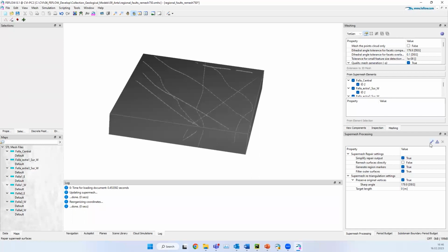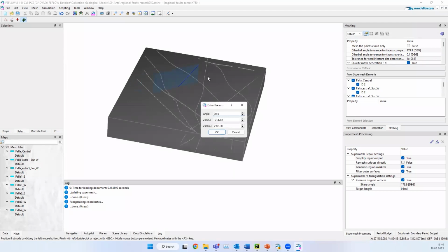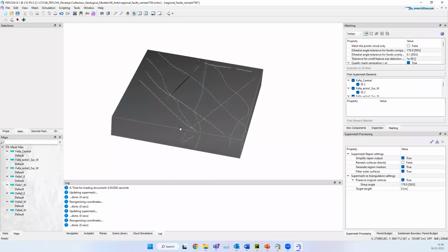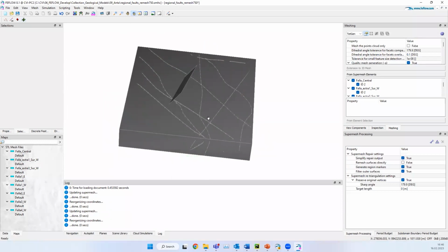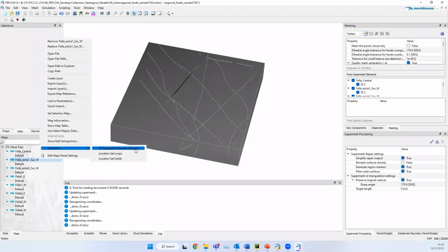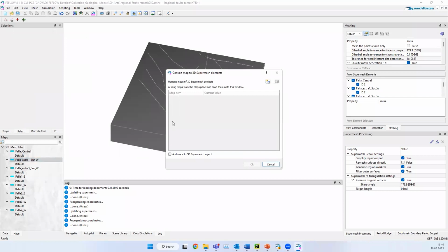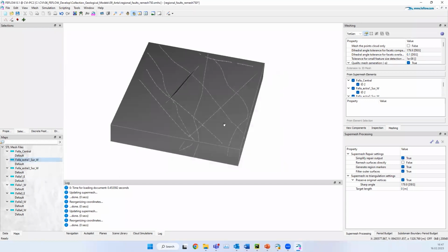So we can use the repair already here. You would like to create faults. So with this possibility, let me draw this, still something to fix with the visualization, but you can define your orientation angle of the fault, let's say 45 degrees, set minimum and max, and then FEFLOW is gonna build your faults. I was showing you before that every time you need to do a right click and then convert to super mesh polygon. So we have changed this. There is the possibility to include a number of files in one single shot so that we do it faster, and so you avoid a lot of manual operations.